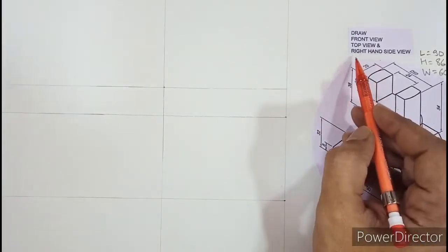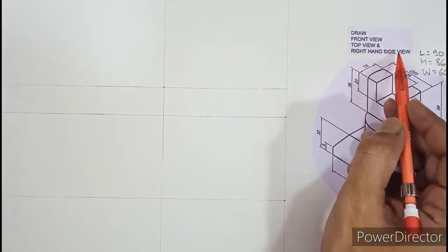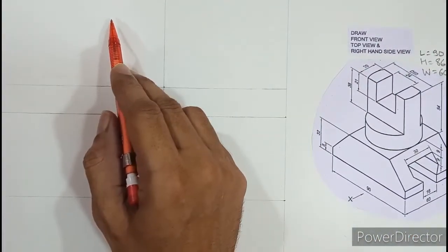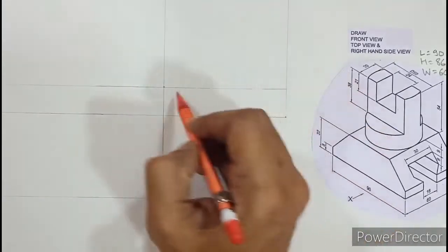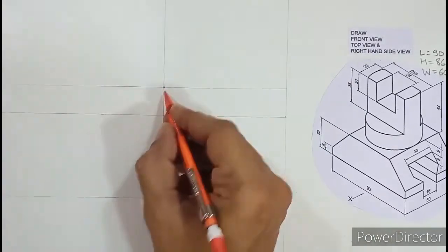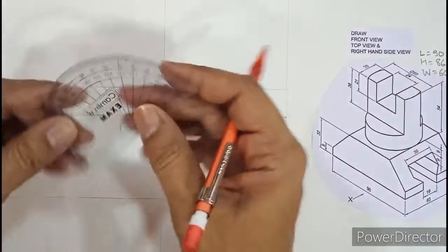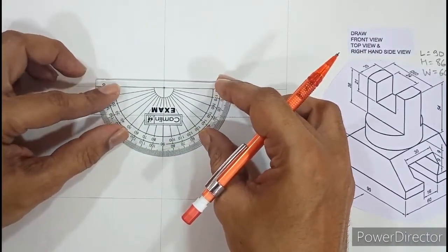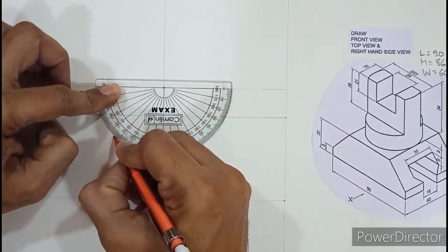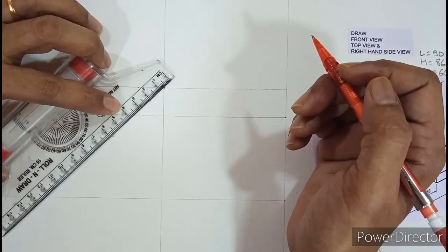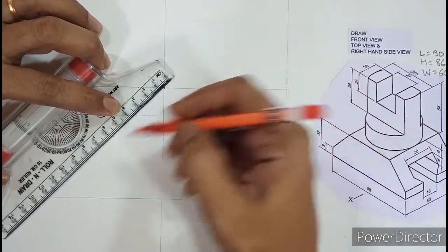Now they have asked us to draw the right hand side view which will be on the left of the front view. So this is the front view box. So on the left side you have to draw the right hand side view. So what we will be doing is, from this front view box, if you look at the bottom left corner from here, we will draw a 45-degree line. Okay, so I will use a protractor, and from here at 45-degree I'll mark a point. After that I'll align both the points together and I will draw a medium dark line.